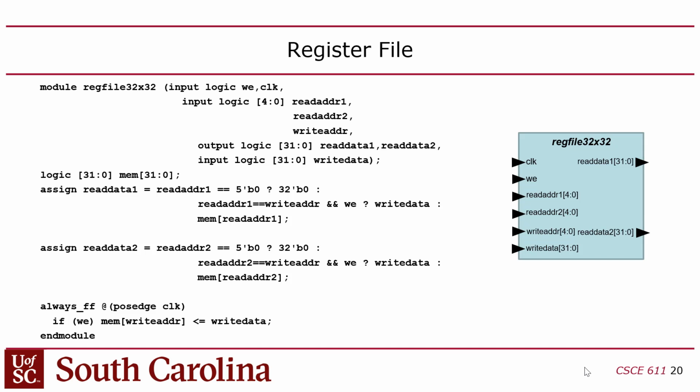Now we make the register file asynchronous for the reads. So the instruction is fetched, and once it's fetched, you're going to read the 2 source operands. Why? Because they exist. The instruction is inside the CPU, and we tie the RS1 and RS2 bit fields directly into the read address 1 and read address 2 inputs, which are your 2 read ports.